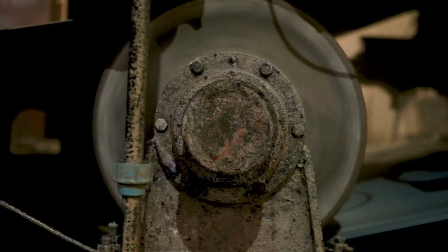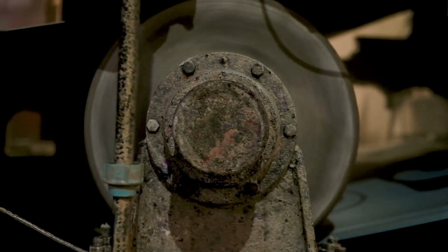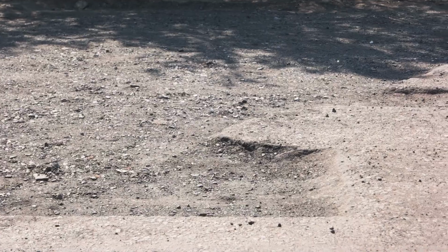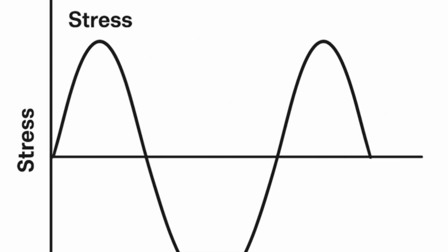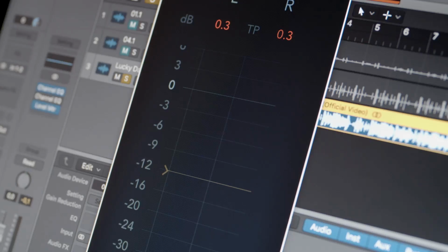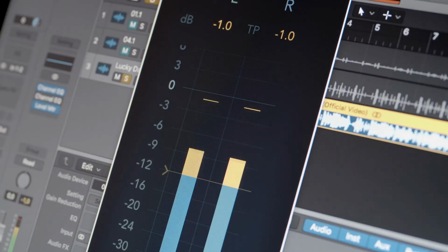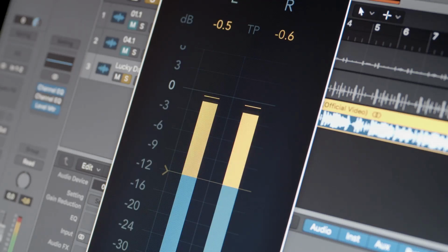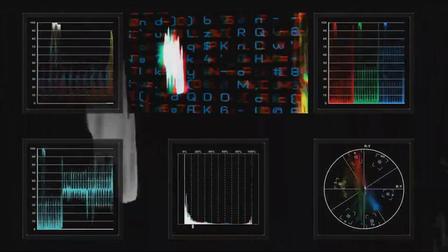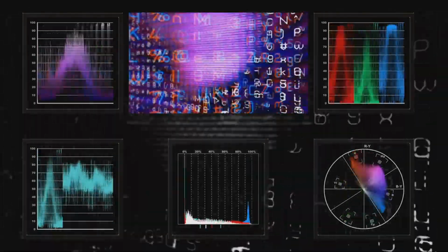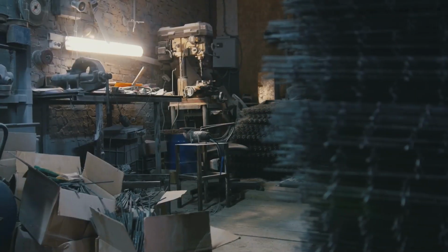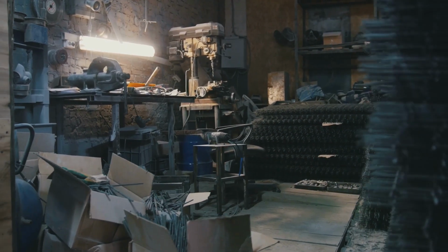Furthermore, components rarely experience simple, constant amplitude, cyclic loading. Think of a car suspension. It sees a complex, variable history of bumps and loads depending on the road surface and driving style. Using a simplified, constant amplitude cycle in our analysis might be misleading. Therefore, employing real-world load histories, often gathered through data acquisition on prototypes or existing products, is paramount. This rainflow counting of complex histories into equivalent cycles allows the epsilon n method to provide a far more accurate prediction of life under the actual conditions the component will face. It's about bringing the messy reality of the world into our precise calculations.